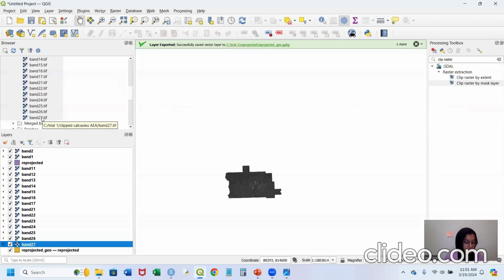Now we are actually merging the band 1 images of the 2 downloaded Landsat image data, and we will do the same for all the 7 bands. Like we'll merge the band 1 2 with band 2 2, and band 1 3 with band 2 3, and up to band 1 7 to band 2 7.